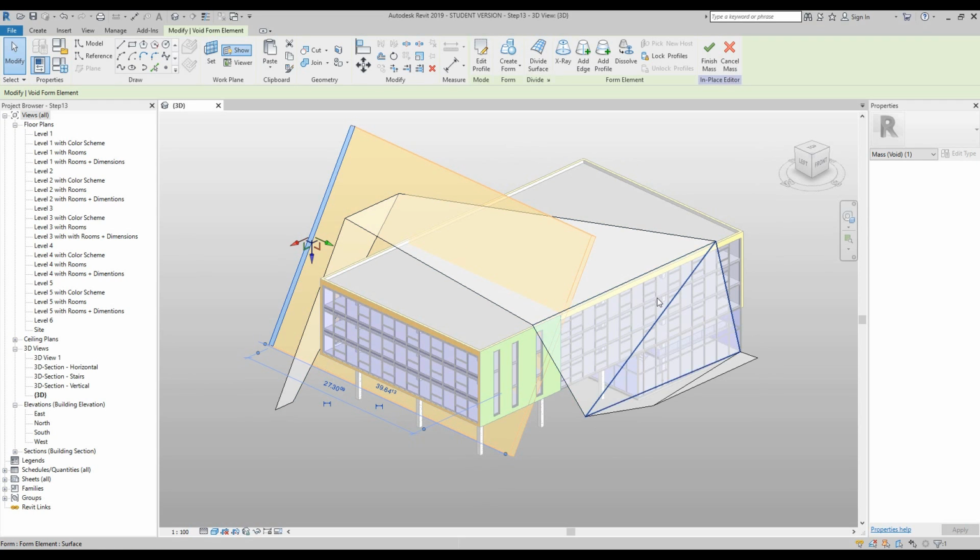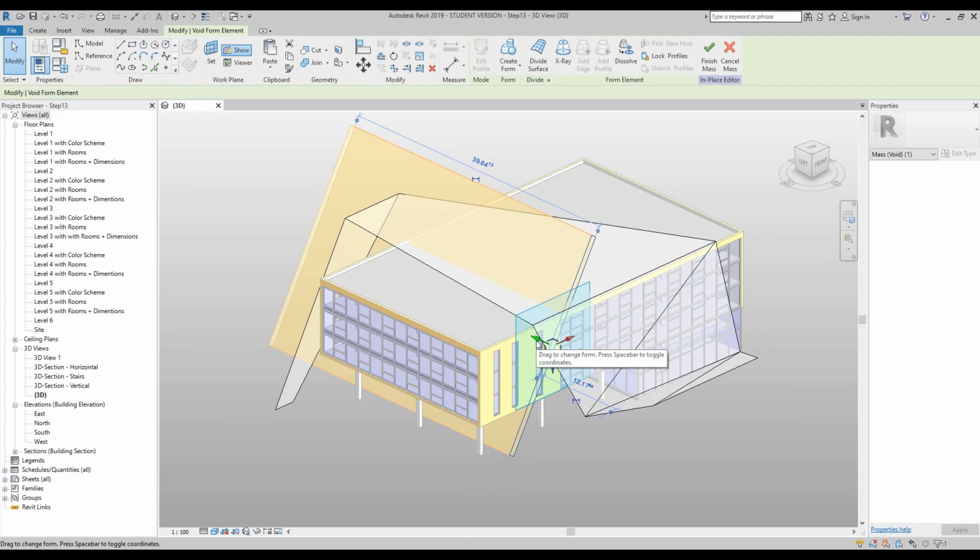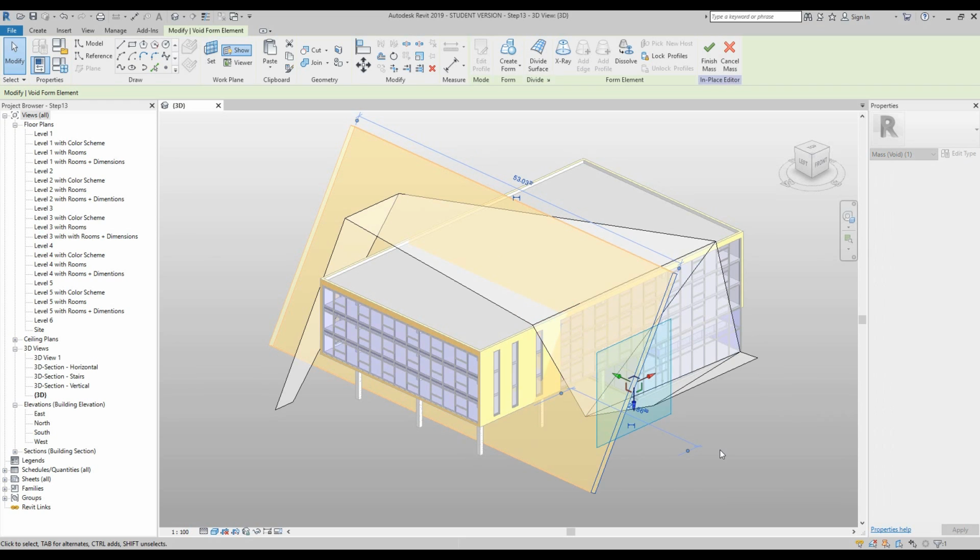Now we also want it to cut a bit of this mesh on the front hand side of the view cube. We want to cut it this side. So if you hover over one of the lines and press tab until you get the face, it was actually 3 times I pressed tab. Once you do that, select it, and again I want you to highlight the green axes and pull it towards you so it cuts this face as well.